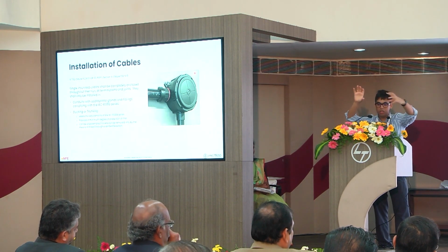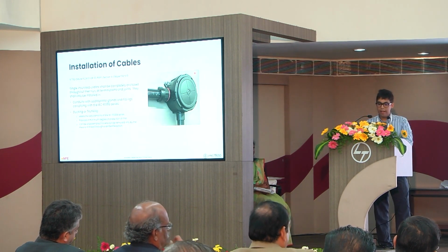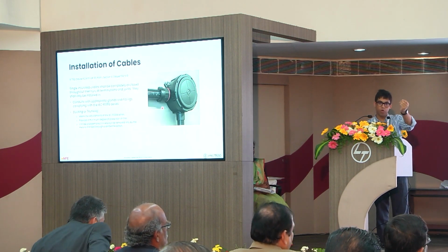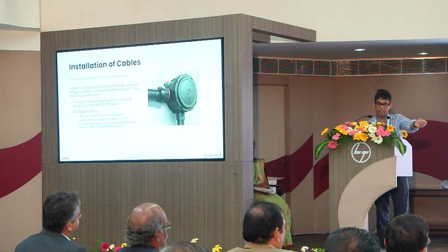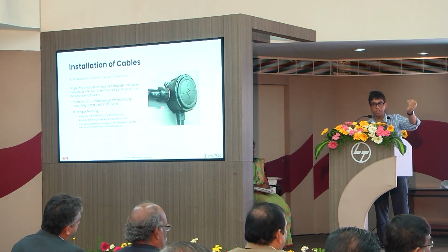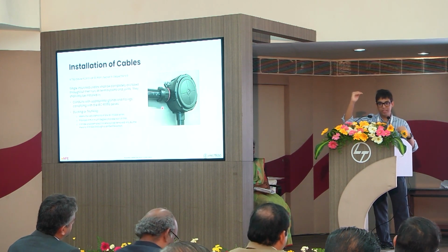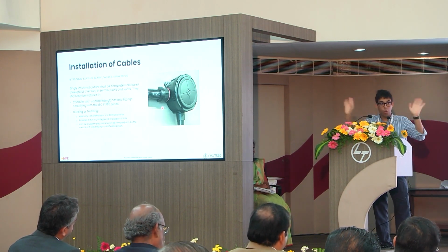Often the hole is bigger or the hole is massive, and then you immediately compromise the IP rating and you don't comply with section 4.2 of IS 732, which is protection against electric shock, because you have single insulated cables that are available to touch. Remember that power pyramid from yesterday? You're only achieving basic protection. The other 3 layers, gone.